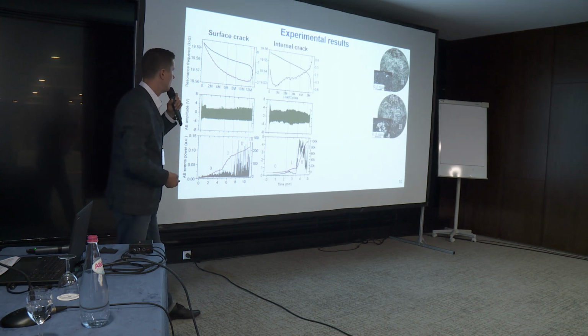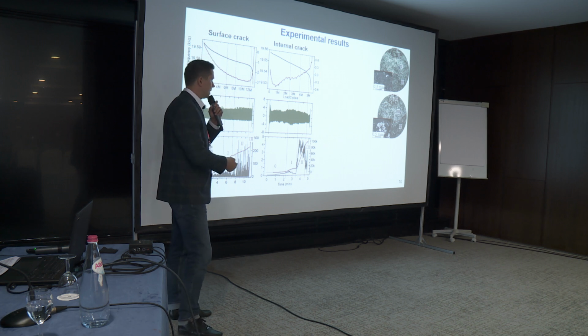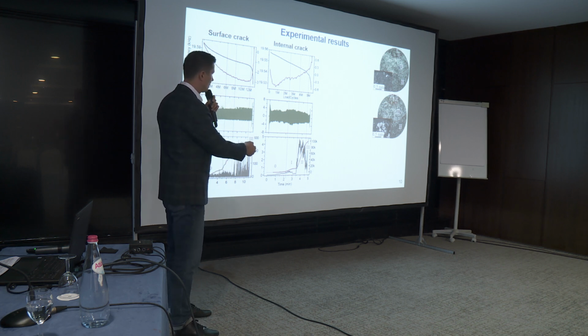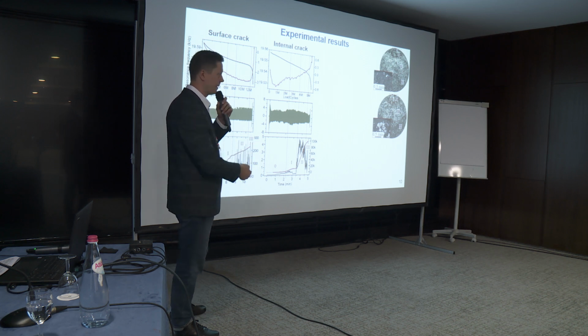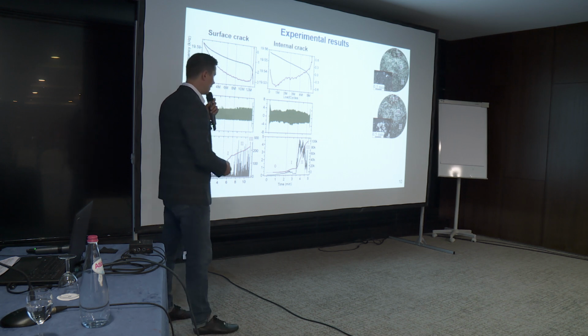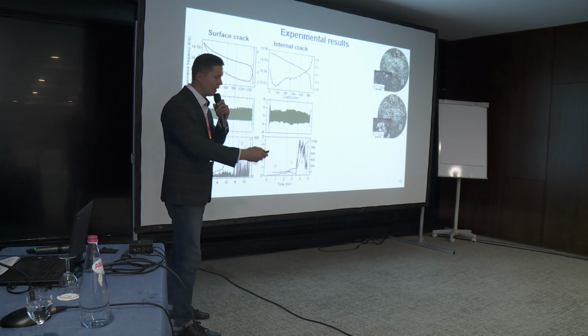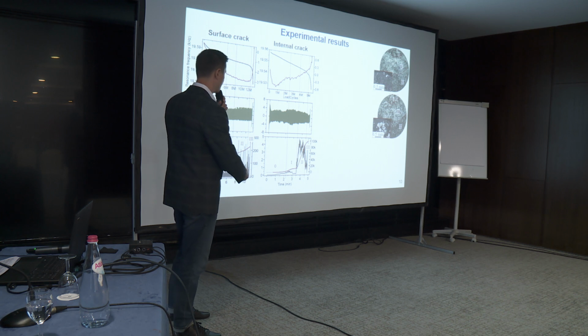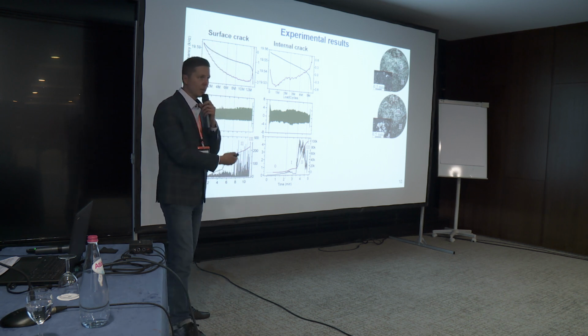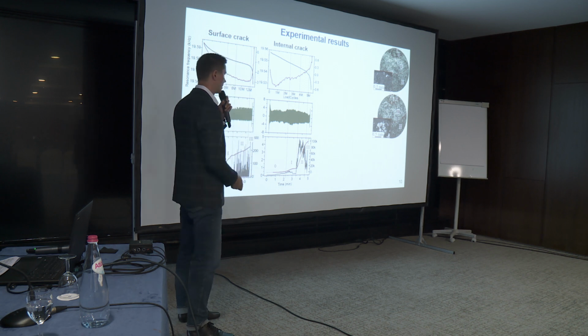Let's move forward. This is the internal crack propagation. You see here in the photo a large cluster of intermetallic phase has initiated an internal crack. It was developing inside the material. And what is interesting, at the moment this penny-shaped crack reached the surface, we have a really high burst of acoustic emission activity. So we could actually hear this. And again, the number of zones somehow coincides with the number of zones in the fracture.